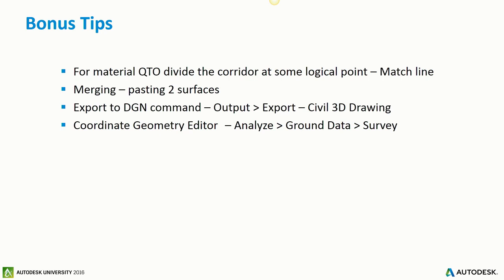You realize that? You can paste two surfaces, the newer surface will come and replace the old. Basically, you got a new Z for the same X and Y, right? Same northing, easting, you got a new Z. That point is good, but because you don't have any control beyond this, the triangulation is going to find a point, any point on the surface, and just triangulate to that. So you are not controlling it.